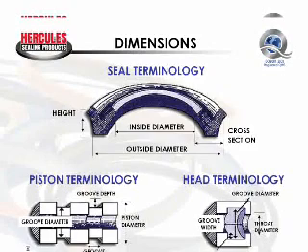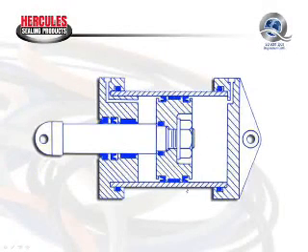Here's an illustration, a cutaway of a hydraulic cylinder, illustrating the static and dynamic seals. This particular cylinder has 3 seals in a static location. Static seals are seals that have no relative motion. So we have 2 end caps on this cylinder. We have an O-ring at each end cap. These seals see no relative motion. They're trapped in this gland area. The O-ring underneath the piston on the cylinder rod, likewise, sees no relative motion. It's trapped in this gland and basically is relatively motionless.